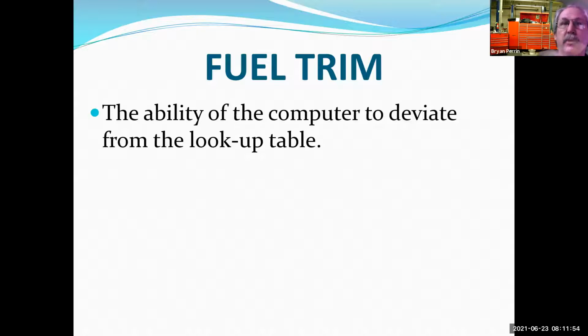So I'm having to hold the injectors open longer to try to deliver the same amount of fuel. Because it's going to delay how soon they open up, and resistance, even 5 ohms, changes injector opening time by about 7%. GM says 5 ohms is not a problem. But 7% of on time, that's a big on time, and we actually can measure that out and see that.